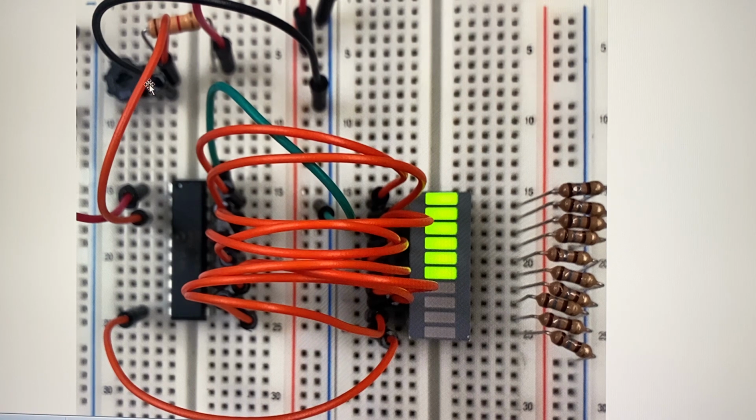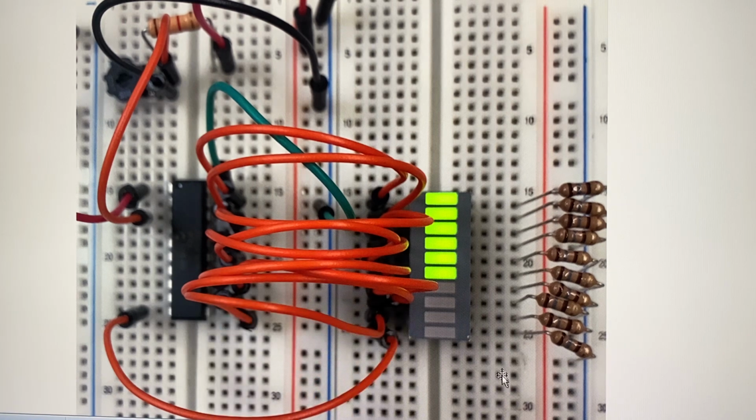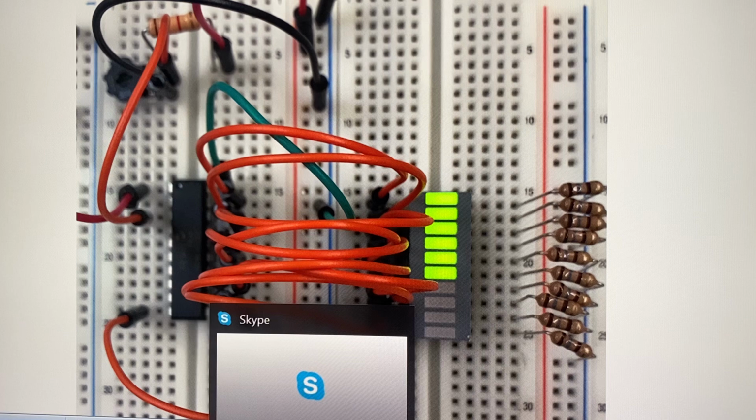And the trim pot has power, has ground, but before going to power, in this case, it has a series resistor to voltage. This is just to protect the potentiometer in case it reaches a value of 0 ohms, to avoid short circuits. Okay. Now we will see the PDF document regarding this practice.